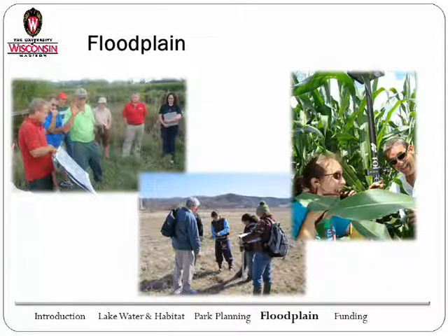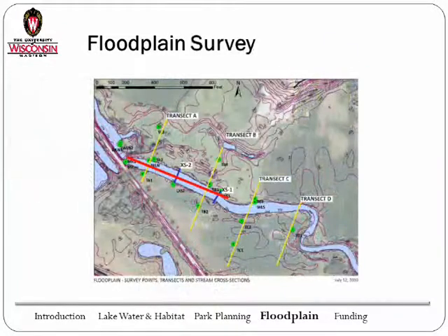Hi, so as Joe introduced, when the dam comes out, the relationship between the stream and its floodplain is going to change a lot. What the dam acted to do was to slow the water and cause some sediment to fall out and build up in the stream and on the floodplain, which I'll go into more today. So the goal of our project, the assessment, is to look at exactly how much sediment has been built up behind the dam.